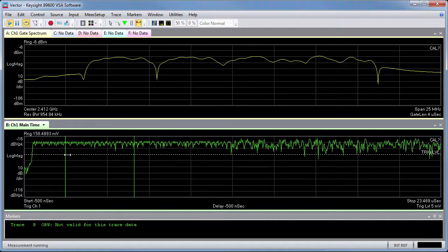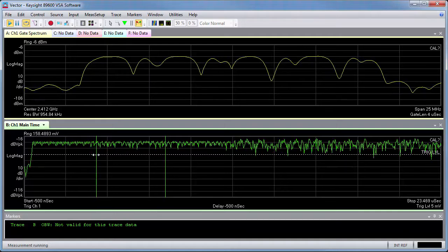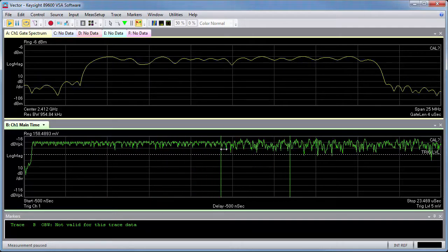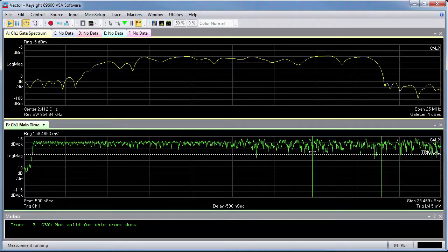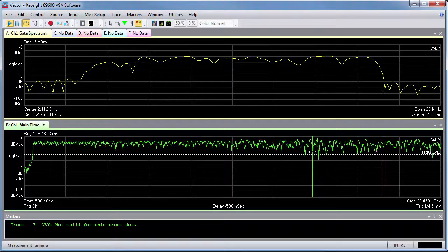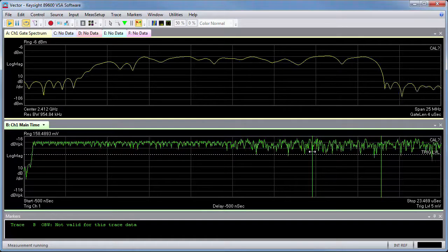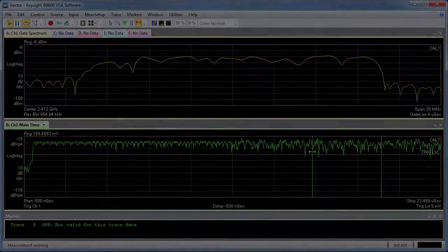Moving to the right, the long training sequence is around 8 microseconds, the signal symbol is around 4 microseconds, and then the rest is data. This looks correct. Therefore, we can conclude that the issue is that the preamble is not long enough. This now gives the direction for fixing the issue. For example, this tells us that an amplifier probably didn't turn on quickly enough.